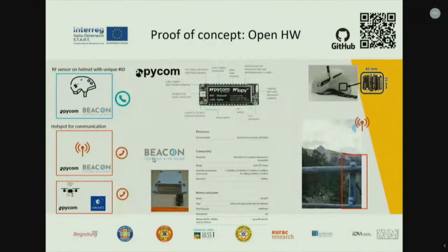We are in the current phase of developing this sensor. At the board level, we are using a PyCom system board, specifically exploiting LoRa, a technology meant for long-range transmission systems. Basically, you can reach up to 40 kilometers in open spaces. In this case, we validated and tested the system and it is reaching more than 500 meters. That is a really good advantage for these mountain operations.